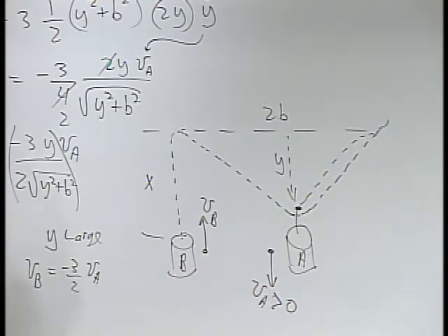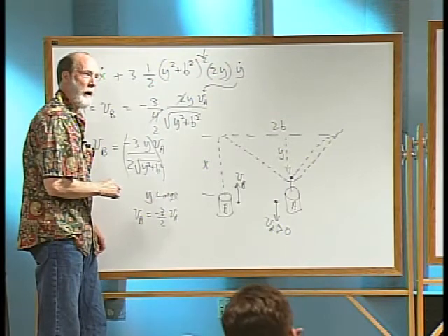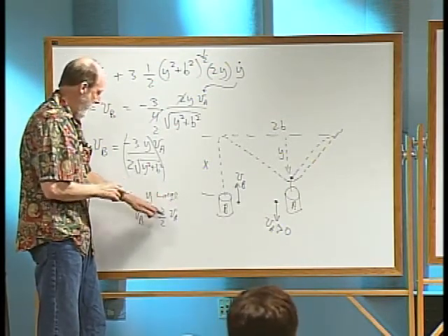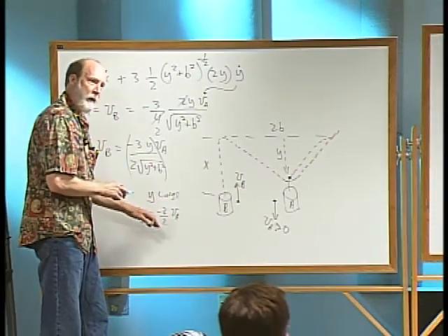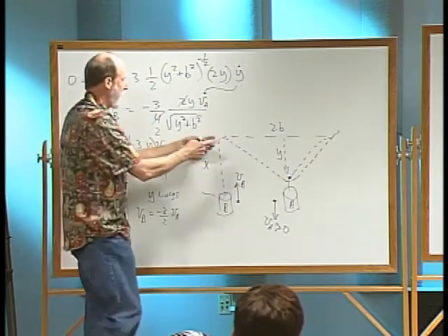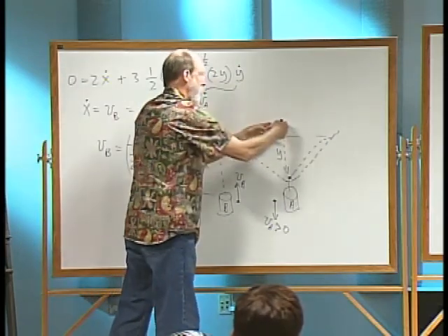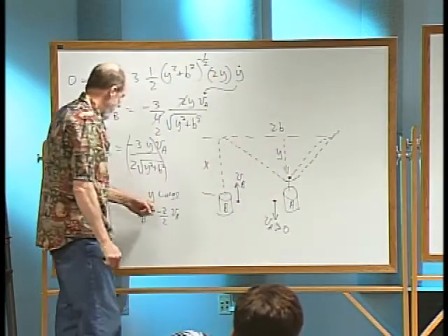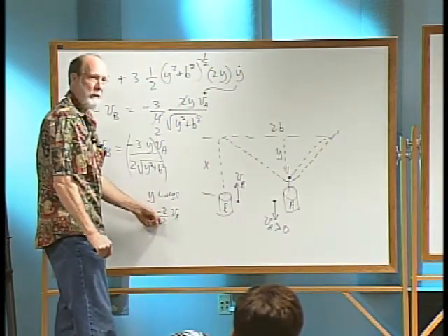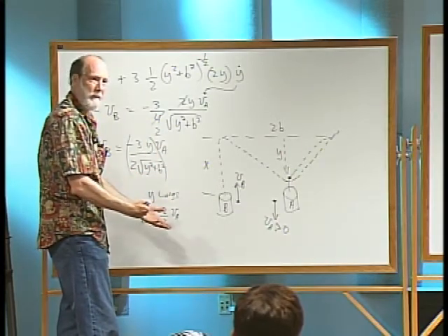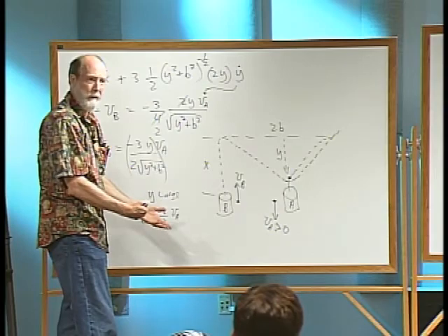And you can see that from the picture too, if you just imagine that they're all vertical, way down there. And so for large y, this would be the relationship. So imagine this pulley mechanism was just close together here, and in essence, this thing hanging vertically. You're going to have a 3:2 ratio in the mechanical advantage there. Does that make sense? Okay.